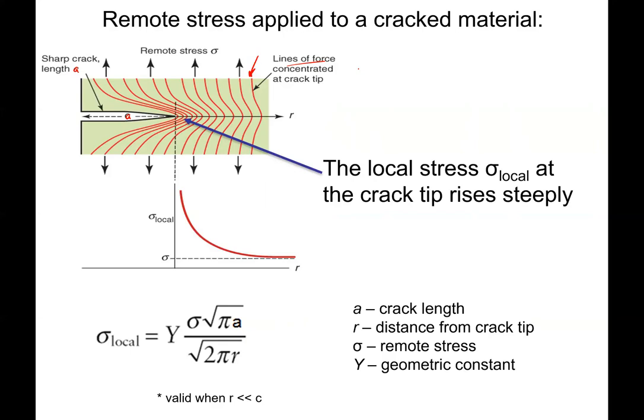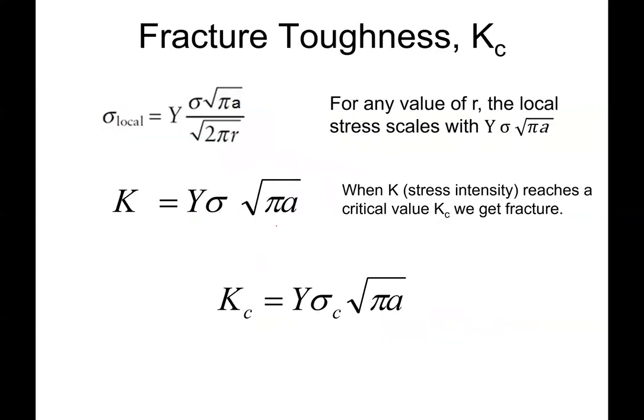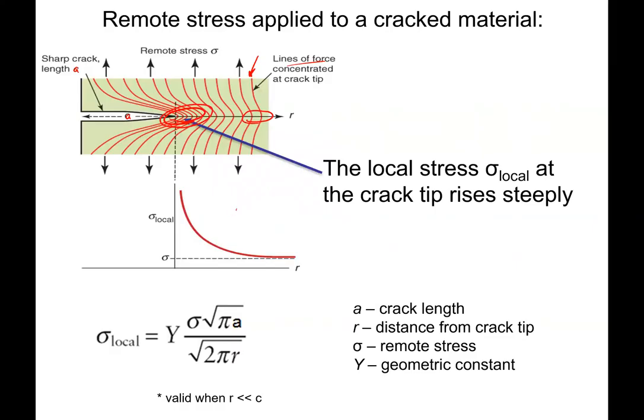It's our stress concentration. You can think of this as a topographical map. So when I get a lot of these together, this means that the stress intensity is increasing. Okay, so I have a lower stress out here, far from the crack, and I've got high stress as I get close to that crack tip. And that's what we've got plotted here.